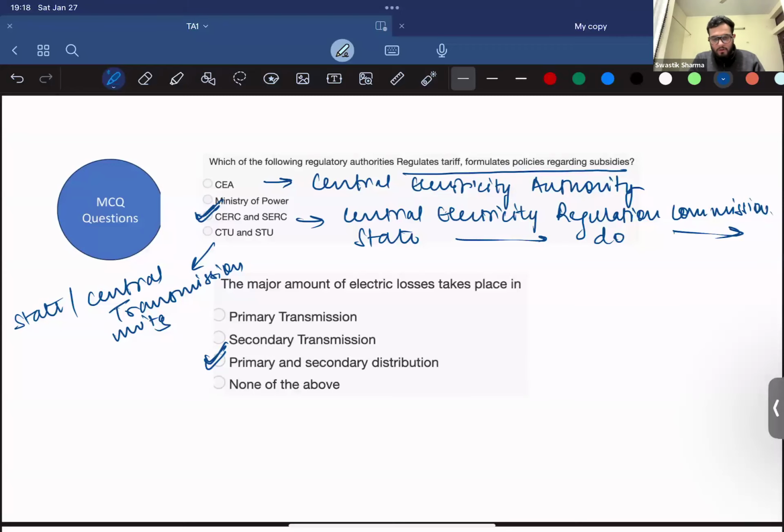It's because the whole electricity distribution system is usually radial. So there are very long distribution lines connected to different segments. This leads to various non-technical losses. The loss can have two parts: it can be either AT&C, aggregate technical and commercial losses, or non-technical losses. Non-technical losses are losses related to, let's say, faulty readings, or bypassing the whole circuitry, or putting illegal connections over the distribution system. This increases losses in the distribution system. These are called non-technical losses.